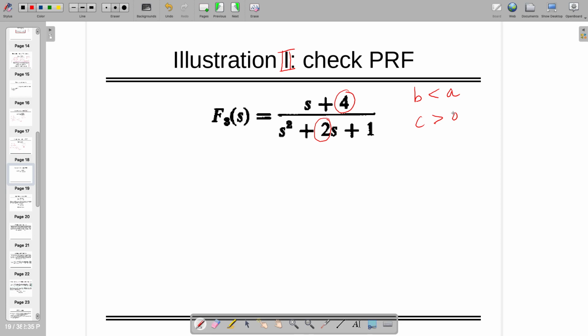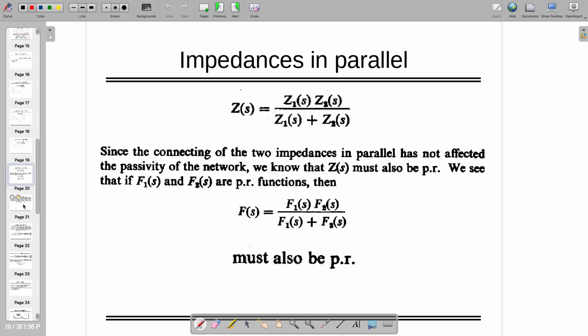By here itself I can say that, because this is the commonly used transfer function if it is second order. So directly by looking at A and B, you can say that no, it's not a positive real function. You can check with m1 m2 minus n1 n2, it will give the same answer, by the way, right? For the sanity check, you can check that B is less than A, so it's not working. Okay, till now all good, so no problem.